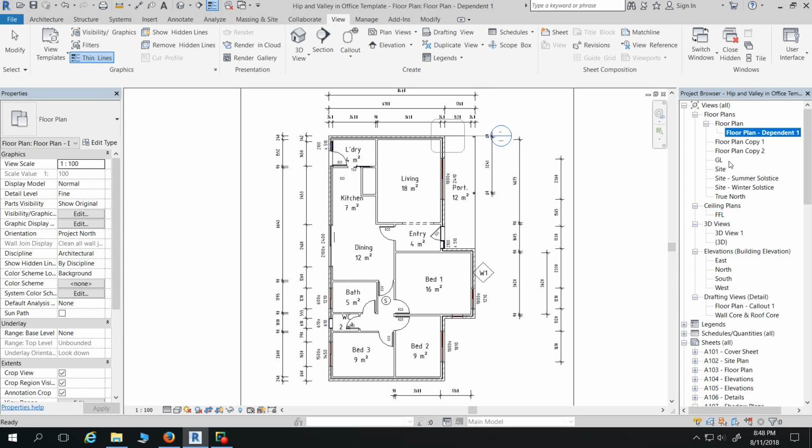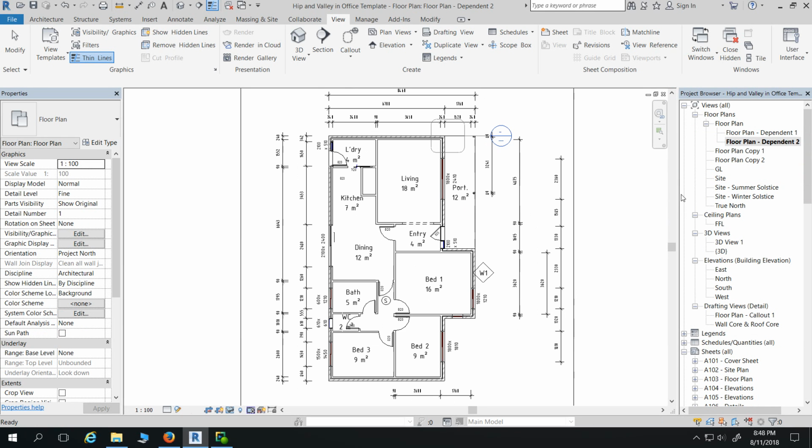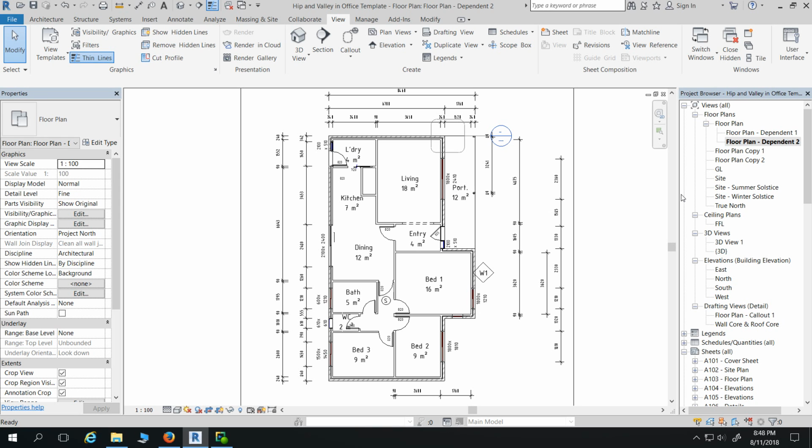It's a bit of a difficult one. The project's too big to fit on a sheet. So if I had a project that was too big to fit on a single sheet at A3, let's say it went over 2 buildings and I didn't have an A2 plotter or something like that, so it went over 2 sheets, you can have part A and part B on 2 sheets.